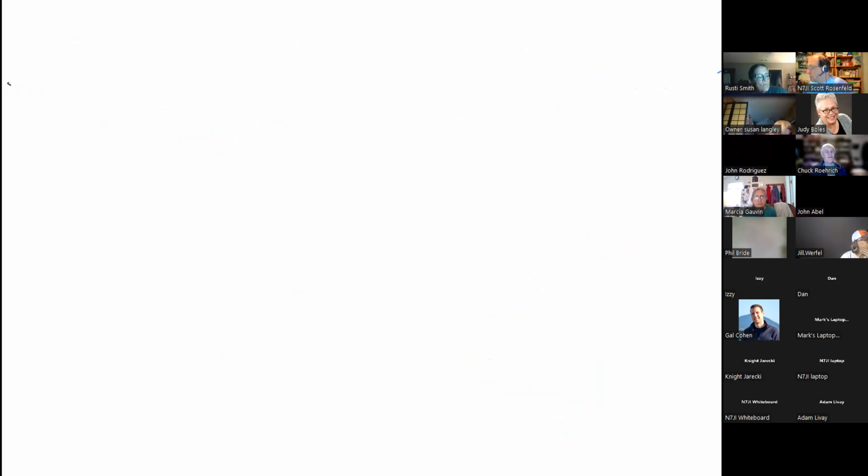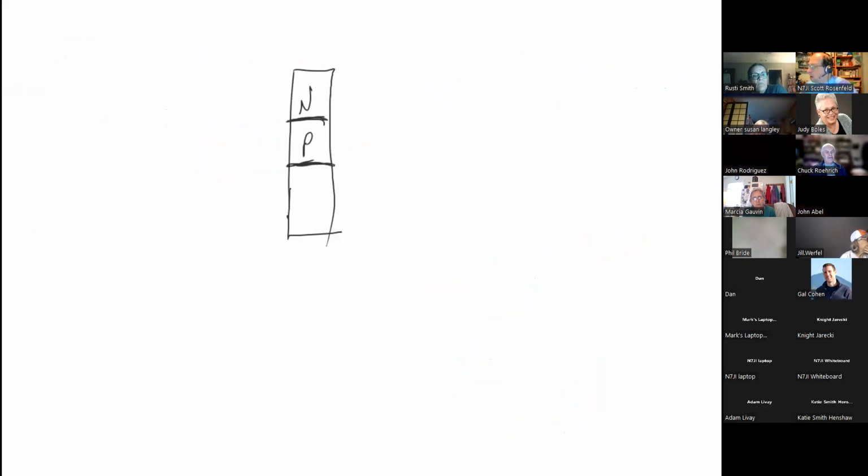But now we're going to take two of these diodes and sandwich them back to back. And we're going to organize them in a vertical format like this. We're going to go NP. So we're going to have an NP junction right there. And then we're going to have a little more P, and we're going to have an N. So really what this means is we can get rid of the dividing line like that, and we can get rid of the letter P. And now notice we have three letters.